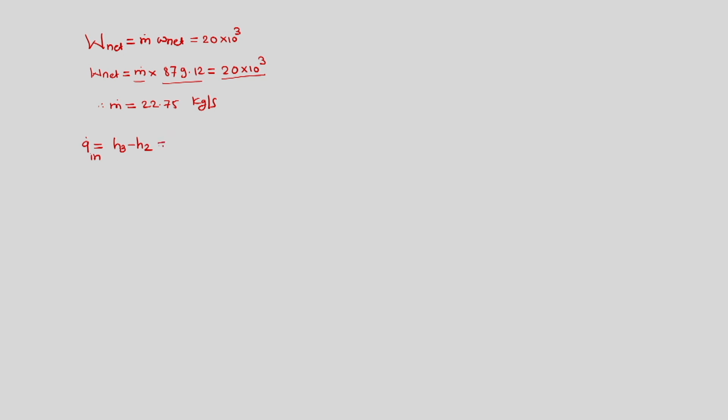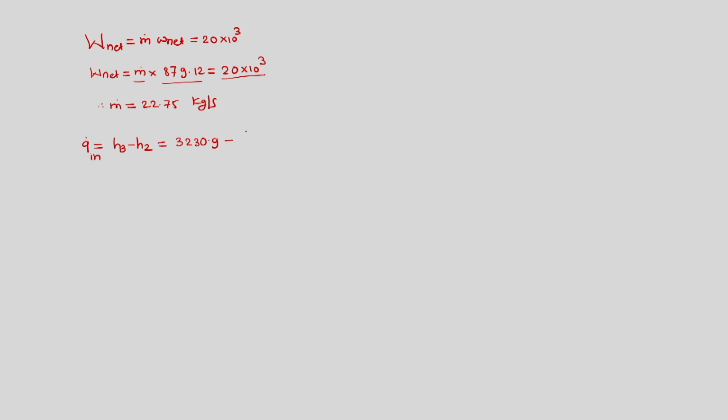So H3 we have known to be 3230.9. H2 is H1 plus pump work. So H1 can be found out corresponding to the liquid saturation enthalpy at 10 kilopascal condenser condition. We have found out the pump work. We need to add that and then get H2. So H2 turns out to be